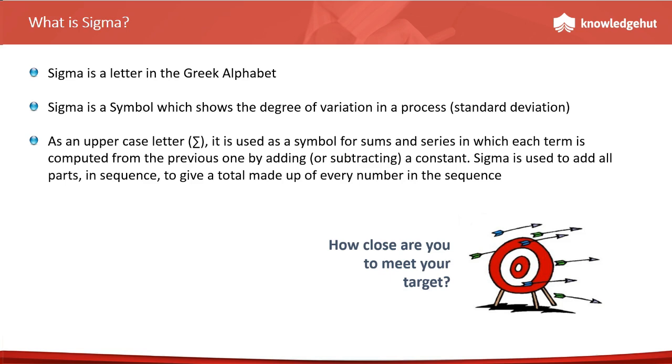So that's what the aim of Six Sigma is. Six Sigma aims at reducing the variation to a level that the entire variation of the process fits within the limits of the customer. At the moment, you might not have a complete understanding of what is Sigma and what is standard deviation, but at a very high level, let's understand what Sigma is. Sigma only talks about how many standard deviations can be fit within the upper specification and lower specification. If you can fit overall 12 standard deviations, that's 6 towards the upper side and 6 towards the lower side of the mean, then your process is capable of producing only 3.4 defects per million, right?